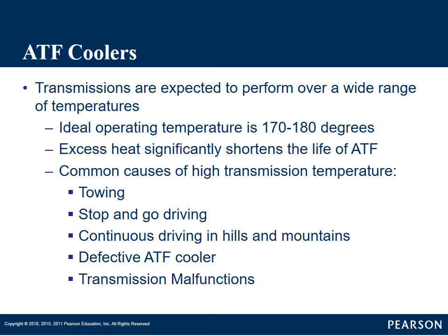Transmissions can operate up to 260 degrees. Ideally, we don't want them that hot, but if you're towing a bigger vehicle or you're towing a lot, you could see that transmission temperature get up there higher. Most average vehicles, once they get up to operating temperature, you're going to be at the 170, 180 degrees.